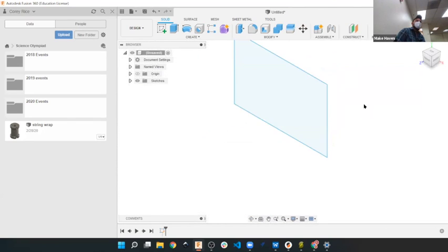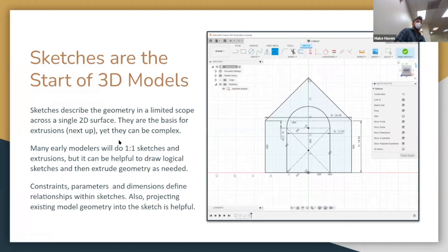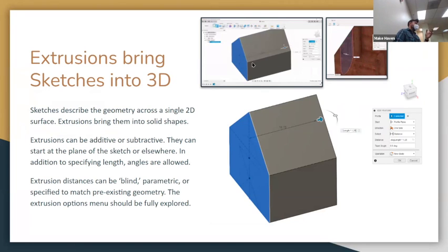And so there's my sketch, sort of oddly floating in 3D now. It's just a weird surface. I'm going to pop this back to the home view. But once you have a sketch, usually the next thing that you do is you extrude. And so a sketch, like here's the doghouse, you can pull that into existence. And this is sort of like the circle on a toothpaste tube. When you squeeze the toothpaste out, you're extruding a cylinder, right? And so it's very much that sort of an action, except with this doghouse shaped drawing, I'm extruding a doghouse. Or you can extrude a negative where you cut away. And so then I'm extruding out the doghouse door, right? And so an extrusion is where you take a drawing and you pull it into the third dimension.